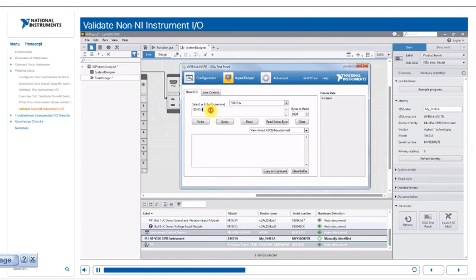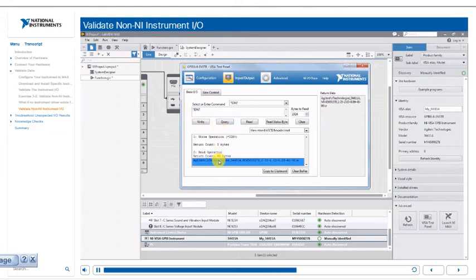As an example, I'm going to do a query on my 34411A instrument with the *IDN? command. This SCPI command returns an identification string from the instrument. Now, I'll do a query with the MEASure:RESistance? SCPI command. This returns a resistance measurement from the instrument.